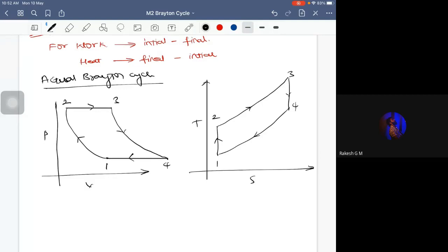Are you able to understand it? Suppose, look here. According to your calculation and expectation, if your compressor is 100% efficient, then it would make state 1 reach state 2. If your compressor is 100% efficient. Suppose it is not, do you think it would trace the same line, or would it deviate like this?